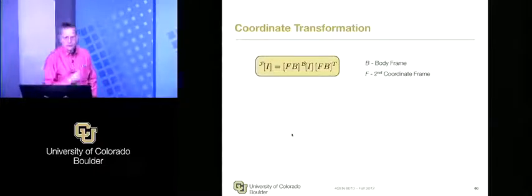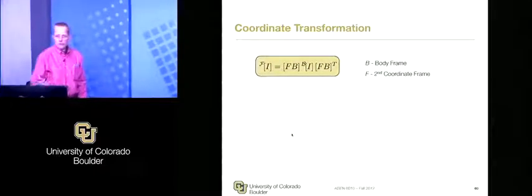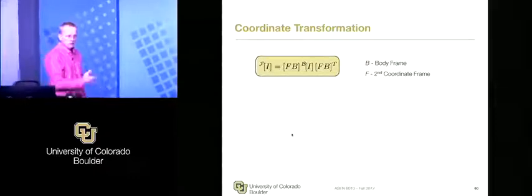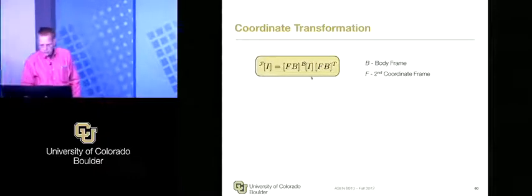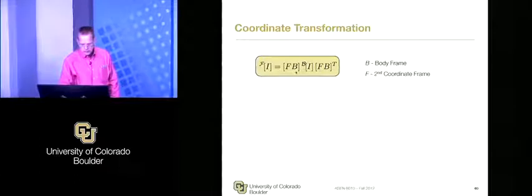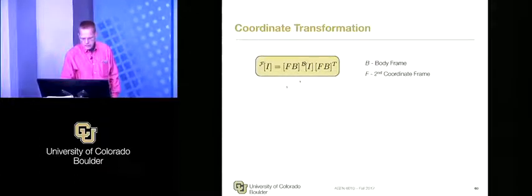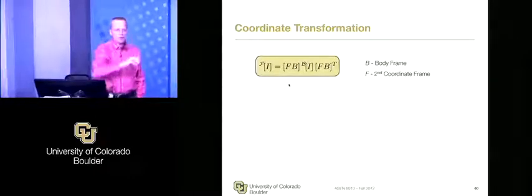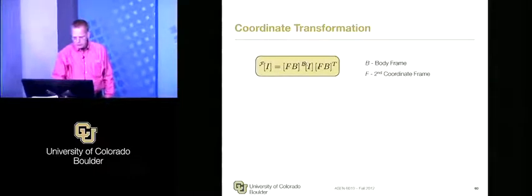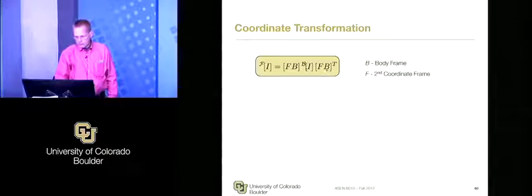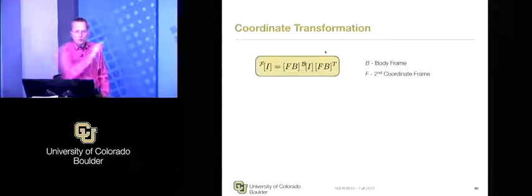Now, if you need a different frame, at the end, you use the rotation matrix, like we do for vectors, with this 2D tensor. You basically pre and post multiply, and with the two-letter rule, if we're doing a vector, v in the B, FB gives me V in F. And the B's have to line up, right? Here, for the matrix, when we pre and post multiply, I need FB, inertia in the B frame, times BF. But I'm just writing here FB transpose, assuming one of them is given.